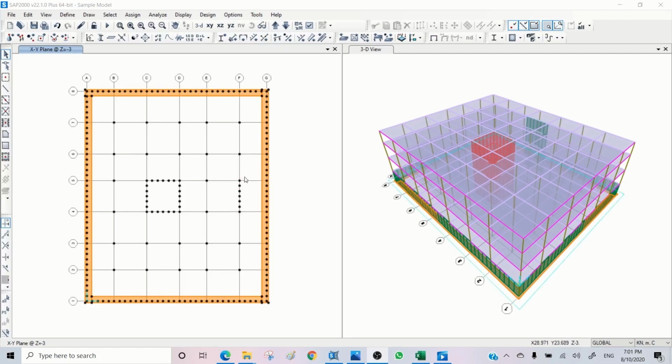I make it a little bit wider, say for example 1.6, with 600 millimeter extended each side. So I'm coming to Draw Special Joint again, and I just need to draw two opposite corners to draw the shell. I don't need all four corners. So I'm coming here and mention this is 0.8 and here is 0.6. So this is one point, the other point is minus 0.8 and minus 0.6.